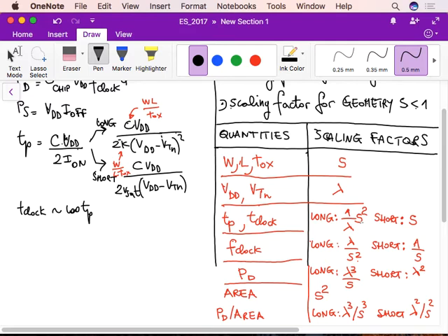It goes down faster for long transistors, and slowly for short transistors. But in any case it goes down. This means that the clock frequency goes up in the same way. If you focus on short transistors, because the formulas are simpler, if I divide every length by 2, I can increase the clock frequency by a factor of 2. And that is of course an advantage.